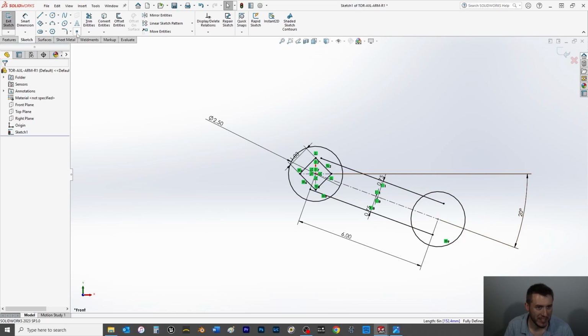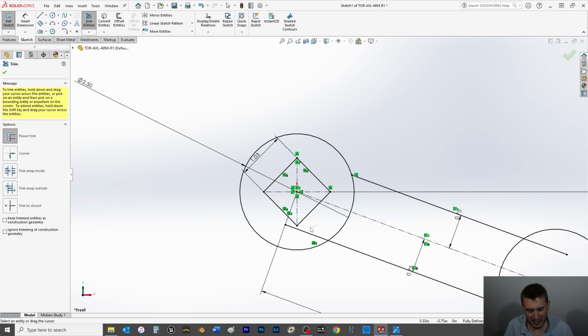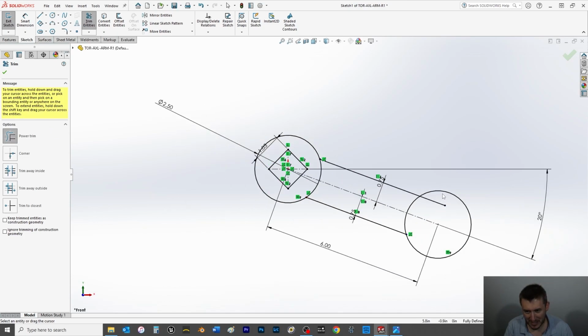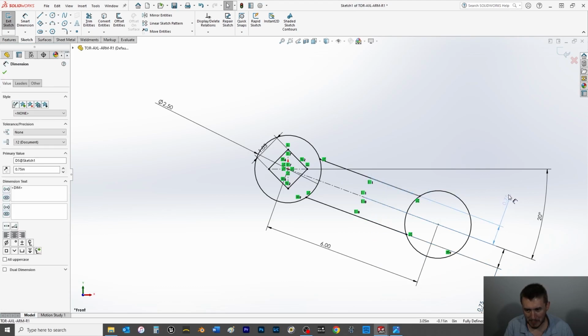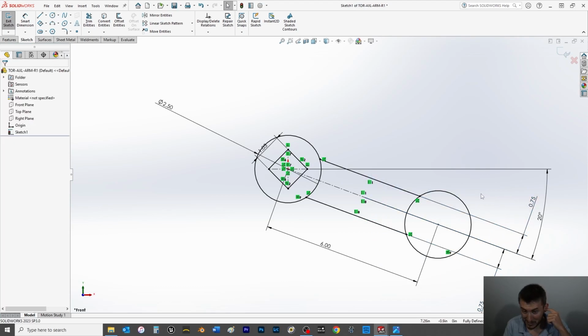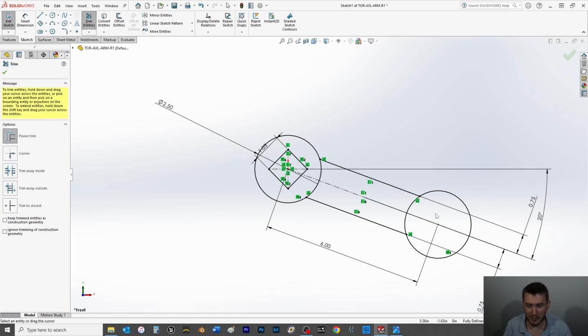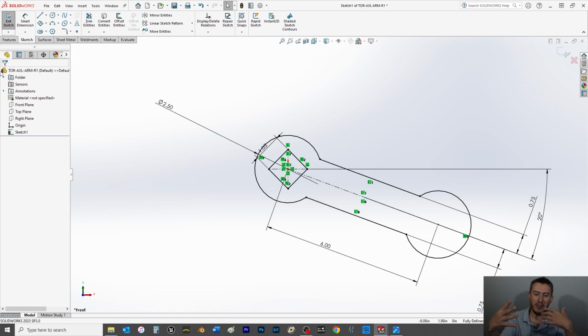Alright, cool. Now we're going to come up here, still in the Sketch tab. We're going to choose Trim Entities. We're going to trim those offset lines we made like such. Here's our offsets. Pull those out of here. Kind of gets in the way of our circle, but that's okay. Now, let's just try it and see what it does. Sometimes when you do trimming, it can disassociate dimensions and/or relations, so let's see how much of a train wreck this becomes if I go through here, here, here, and here. It maintained it. I like it. That's less regions I'm going to have to select in the extrusion portion of things.